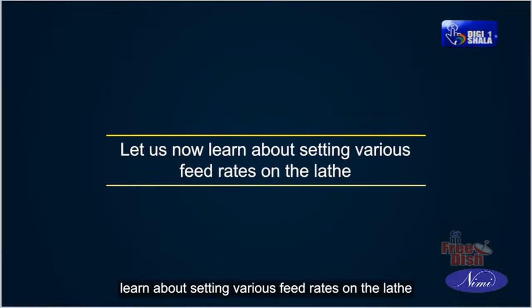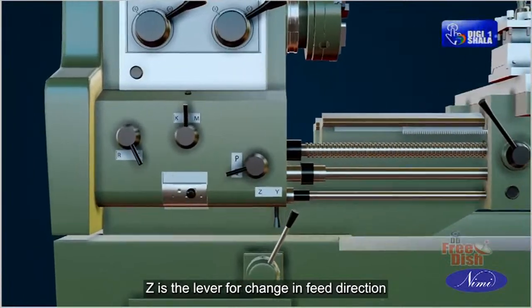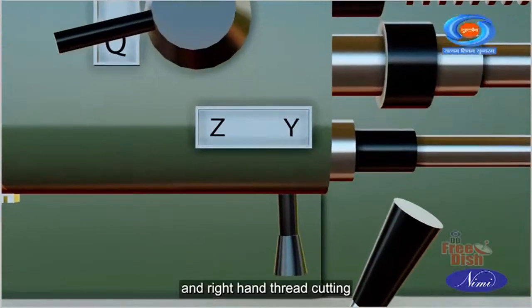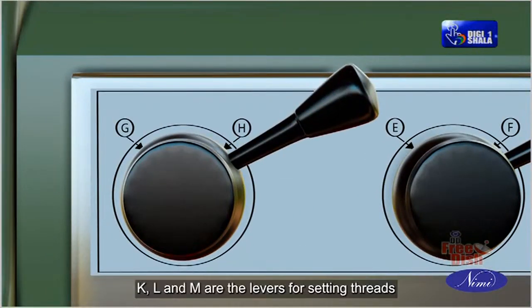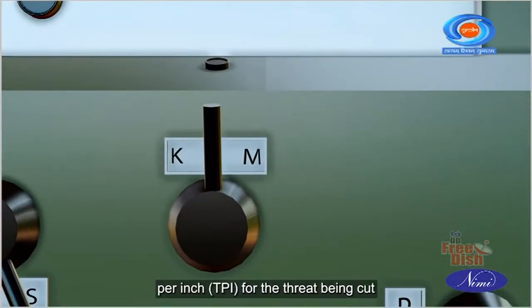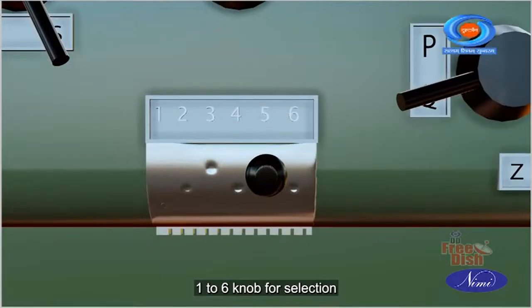Let us now learn about setting various feed rates on the lathe. Z is the lever for change in feed direction. Y is the lever for left hand and right hand thread cutting. G and H are tumbler gears. K, L and M are the levers for setting threads per inch (TPI) for the thread being cut. 1 to 6 knob for selection of feed thread pitch.